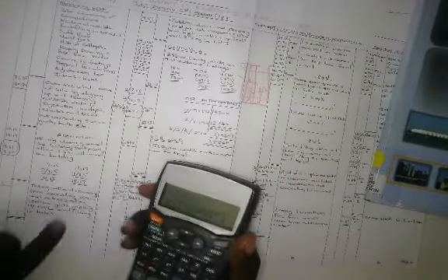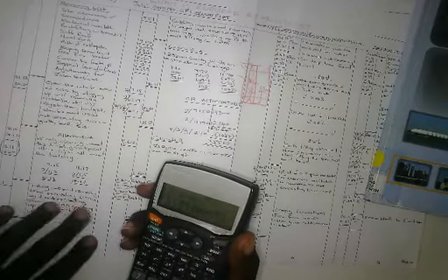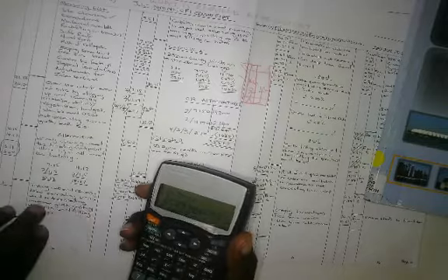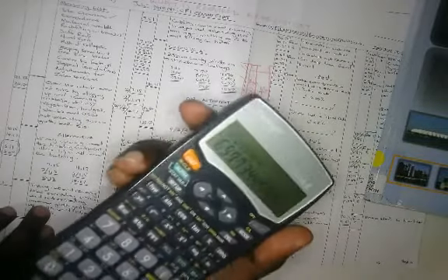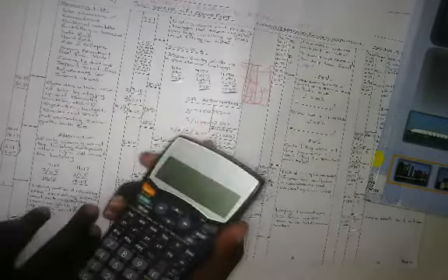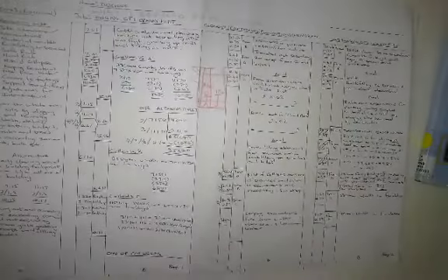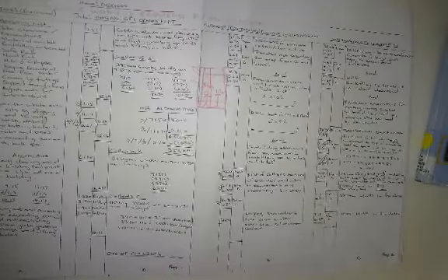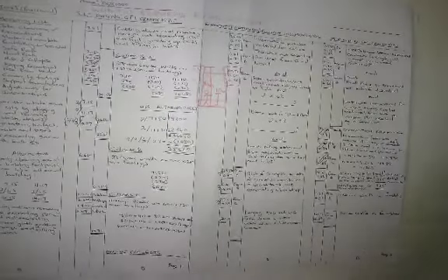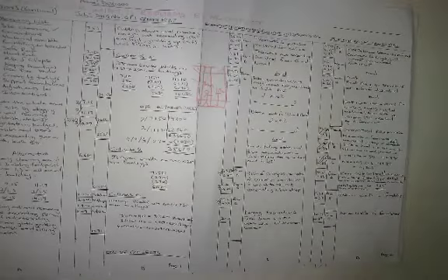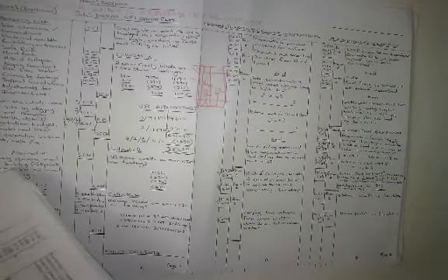Now the standard system tells you that you need to group your trees: it's either exceeding 200 millimeters, not exceeding 500, or exceeding 500, not exceeding 1000. So this one clearly the girth does exceed, it's 659, so that exceeds 500 millimeters, guys. So don't forget the formula. Calculating the girth of a tree, it's your pi times the diameter of your tree. Fine, okay, fine. And then you're going to cutting down and removing hedges.